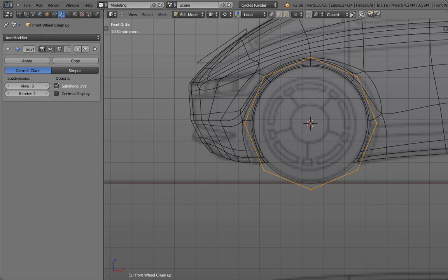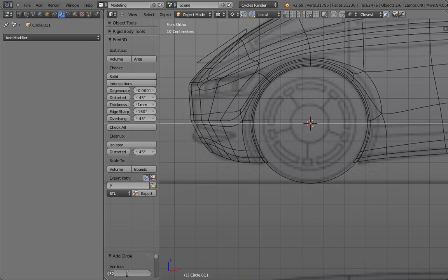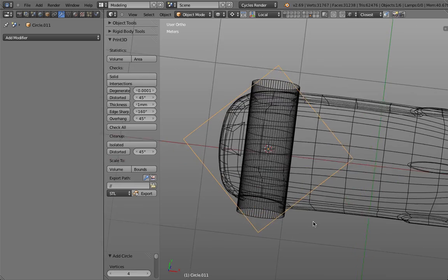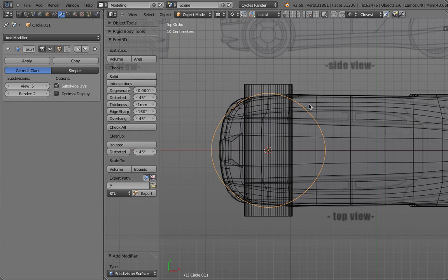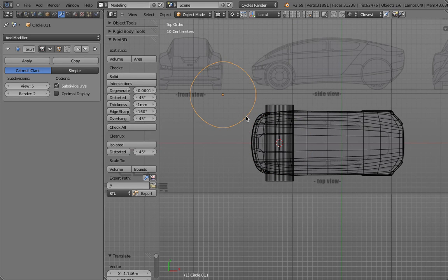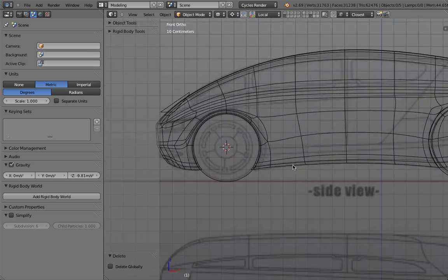Also, a small heads up: you see the cylinder is made out of 8 points. So everything that is bigger than 6 points will turn more into a perfect cylinder. If you make a circle, for example, with 4 points, this is not going to turn into a perfect circle. So you see that it looks more rectangular with rounded edges. So whenever you create geometry in Blender, when you want to cut something, maybe use 8 points or 12 points. The more points you have, when we bring it into Fusion and T-splines, the better the ring will really be circular. Okay.